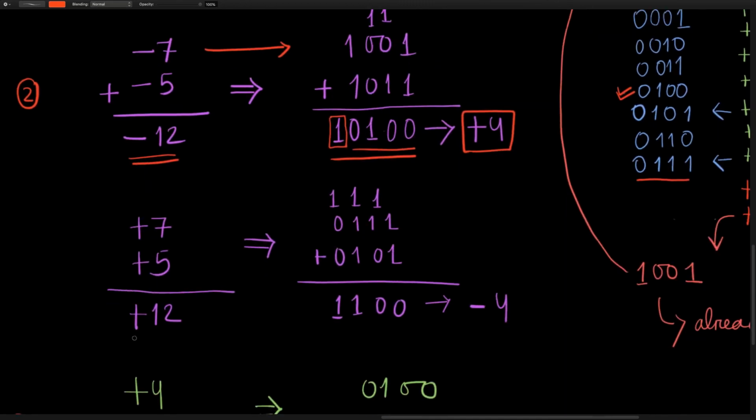The very same thing also happens here. The answer is negative 4, which is not right because the answer should be positive 12. We need 5 bits to represent that signed binary number. This is only a problem with signed binary numbers. If we take only simple binary numbers, then we might represent it with 5 bits. Signed binary numbers means the leftmost bit is reserved for sign.